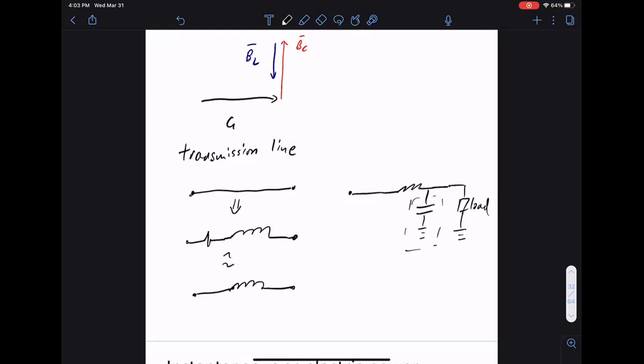So if you walk around your neighborhood, sometimes you'll see this sort of big box on some yards. You see this square box. Let's not touch it, this utility box. Often that's a capacitor sitting there trying to cancel the inductor out. So if you walk around next time, you can pay attention. You'll see these kinds of boxes out there. So that's when we put a capacitor to ground, trying to cancel the inductance on the line. You want to basically get your load to be more capacitive.